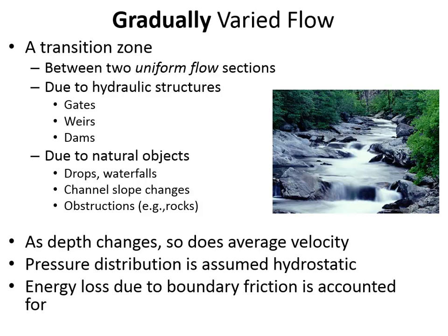Now, what we have to know is that when the depth is changing for a certain flow rate, so does the velocity. And so what's going to complicate matters in the methods that we learn in future lectures is that the velocity is changing, and so when we calculate the velocity head at a point, for example, that's going to be changing right along with depth. And so we're going to have to learn methods for finding the average of flow conditions between two sections. That's sort of the heart of the numerical integration method we'll get to next time.